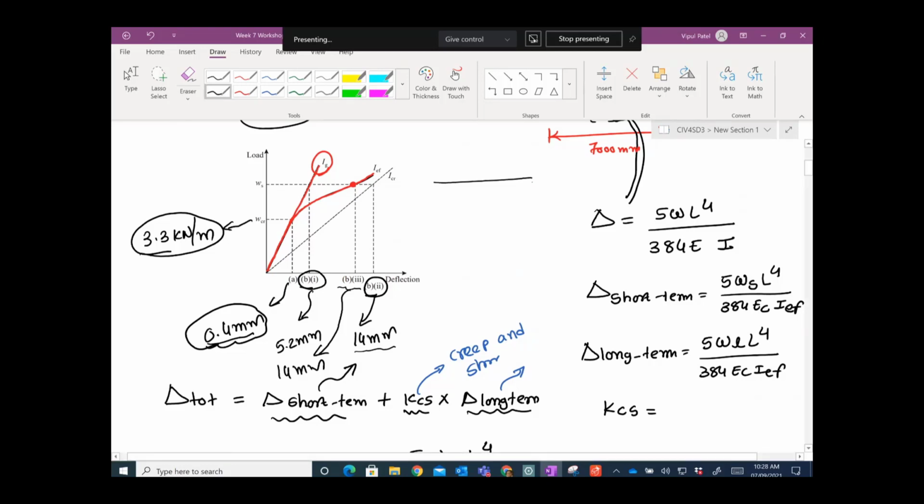You remember that when your beam is going to crack, you say okay, don't worry about this region. That's what happens here, I crack. Well, in reality it's not correct, right? In reality your beam will crack, but the concrete between the cracks will have a tension resistance, that is called tension stiffening. So for that reason you have some resistance, some moment of inertia, in these regions as well.